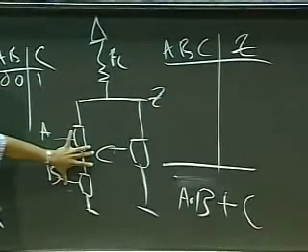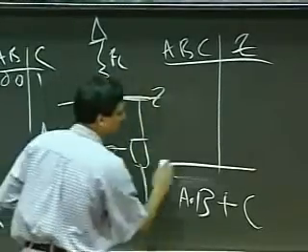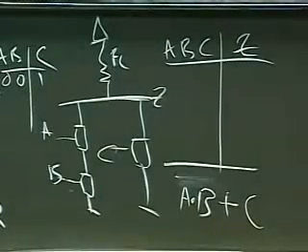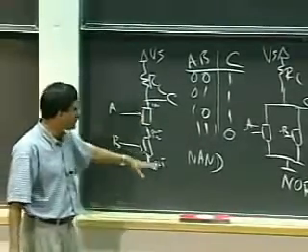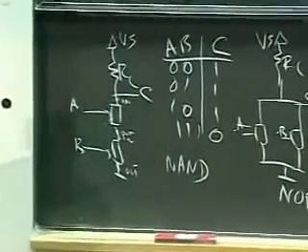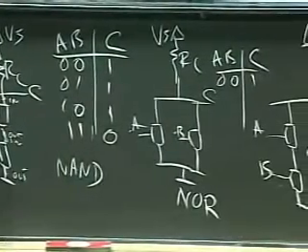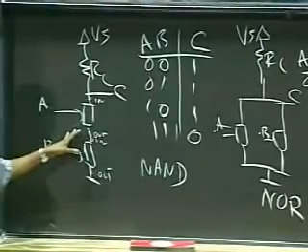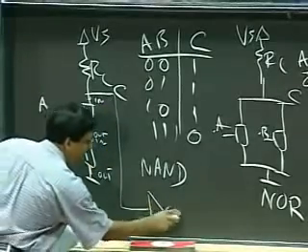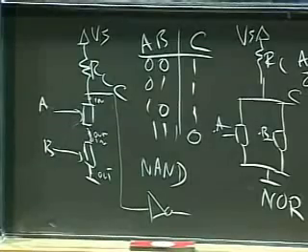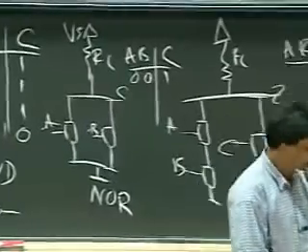So this is my A dot B. This is my plus because of a parallel shunt here. And ultimately, this causes an inversion in this gate. Our primitive pattern has a generic inversion built into the output. That is why we commonly end up building NAND gates and NOR gates as the simplest gates. We don't build AND gates and OR gates. How can I convert this one to an AND gate? Anybody? Put an inverter on the output. So I take this, put an inverter here, and I get an AND gate. The real primitives in circuits tend to be NANDs and NORs.